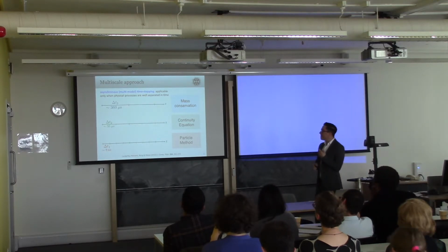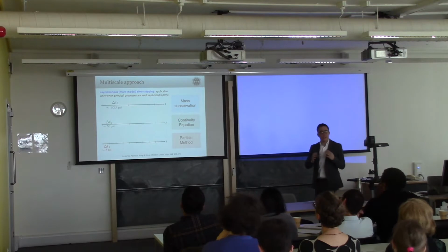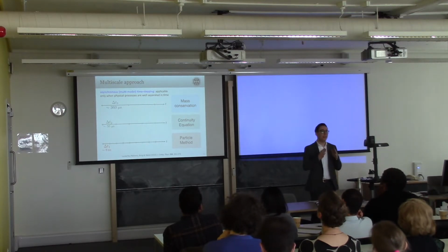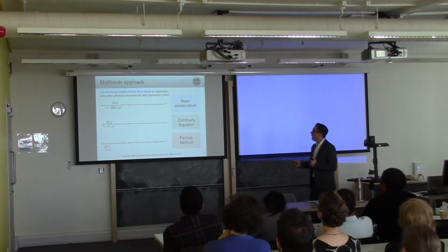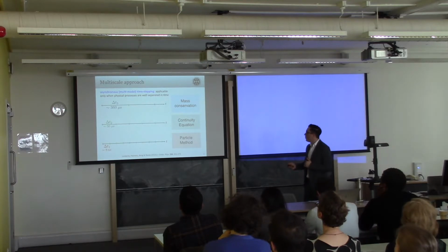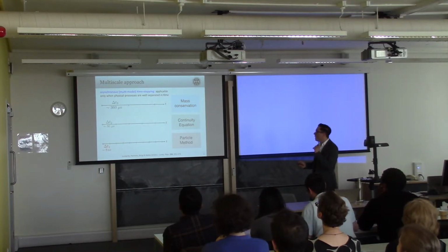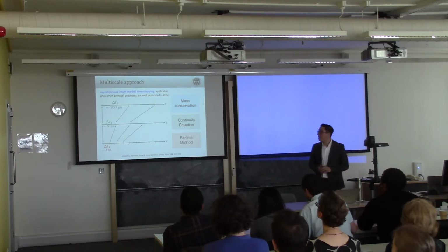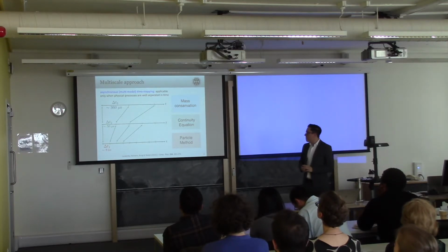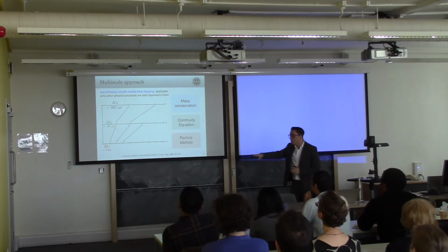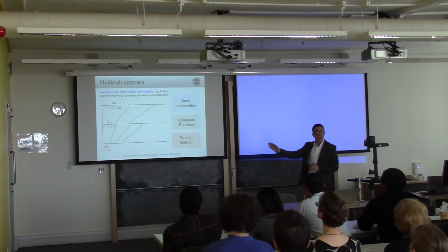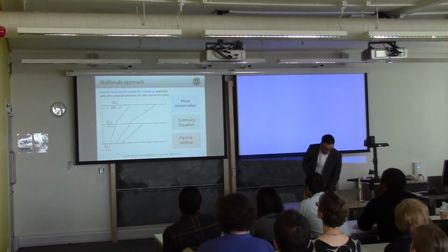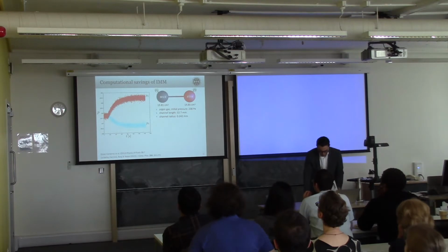So what we've come up with is an asynchronous time stepping method where we say, provided that the scale separation of the physics is well separated, then we can reduce the time step to something a bit more affordable, but we couple at each and every time step. So this allows the conservation equation, the PDE at the top, to fast forward quickly in time and reach the 100 seconds that we want to target, whilst the particle method is in quasi-static equilibrium. So how does the method work?